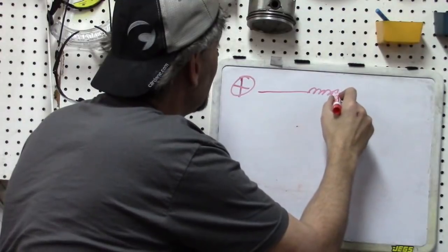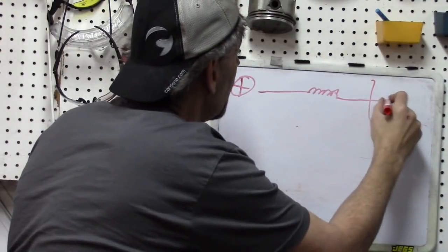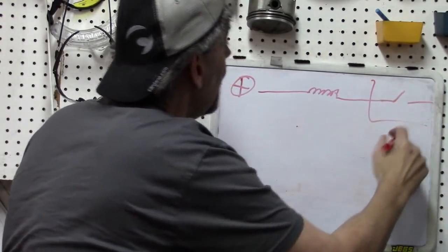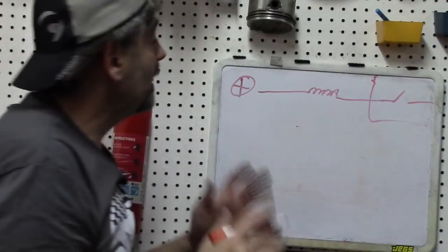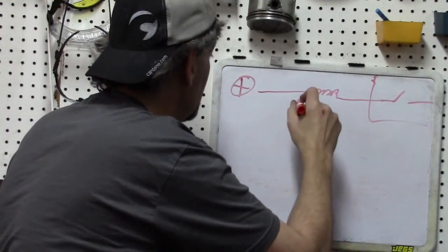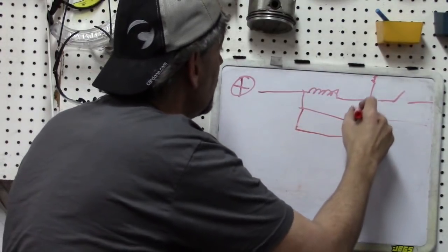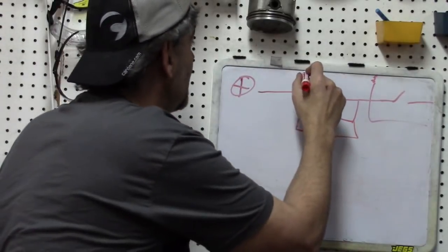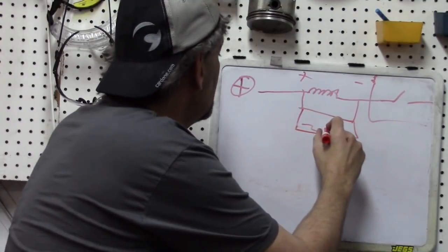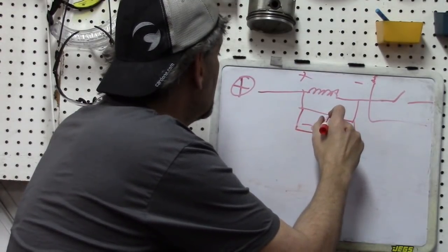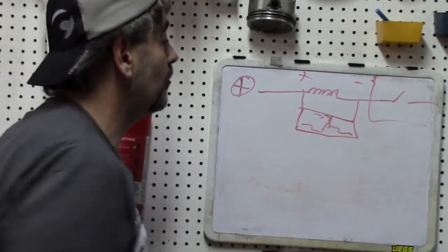Okay, let's do the 2-wire system. We're going to have our PCM here with our internal switching by the PCM. Of course, that's going to be transistor modulated. We know all this. And what we would do is we would take our scope, of course, and we've done this in the previous video. We look here and here on the positive and negative, right? And the scope is going to show you that pattern that we discussed, with that big voltage spike there.